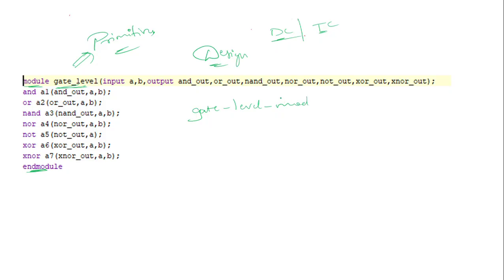You can write your own name also, but the name should help you identify which type of code it is, even some days later. You can use any name, but don't use keywords, because there are inbuilt keywords in Verilog, so don't name modules with keywords.